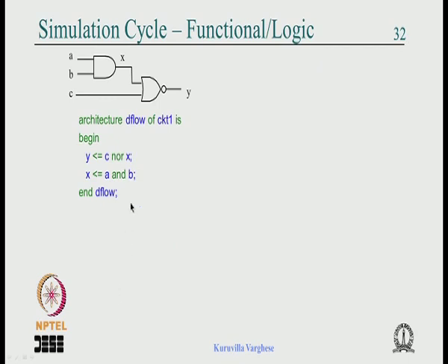but in this case there is no delay. Okay. So A changes at 100 nanosecond, but X is also changing at 100 nanosecond, and Y is also changing at 100 nanosecond. If you are writing the software for the simulator, there is an issue, because A changes at 100 nanosecond, now simulation time is 100 nanosecond, then X is changed at 100 nanosecond and the simulator comes back to 100 nanosecond, because everything is at 100 nanosecond.